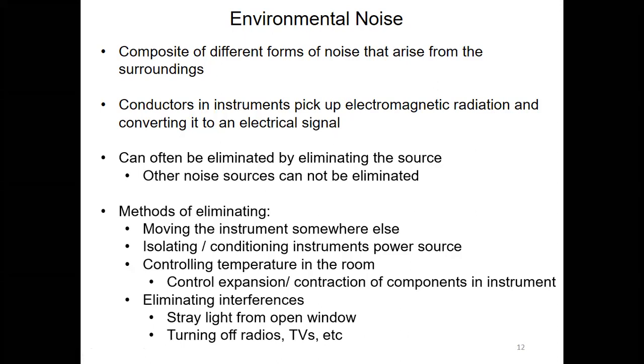One reason for that is to control the temperature, right? By controlling the temperature, we can minimize or eliminate some thermal expansion of the instrumental components. So that is one way to remove environmental noise.